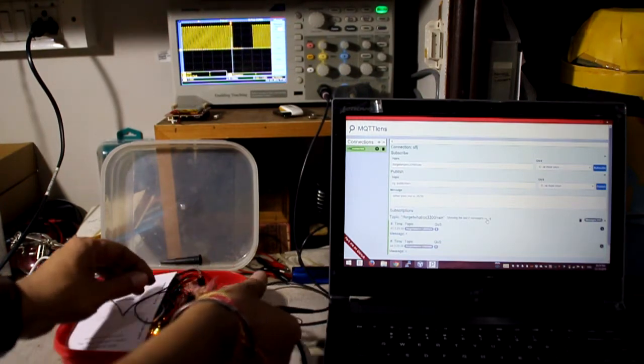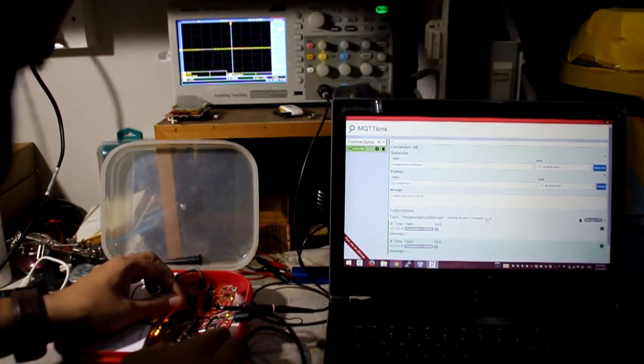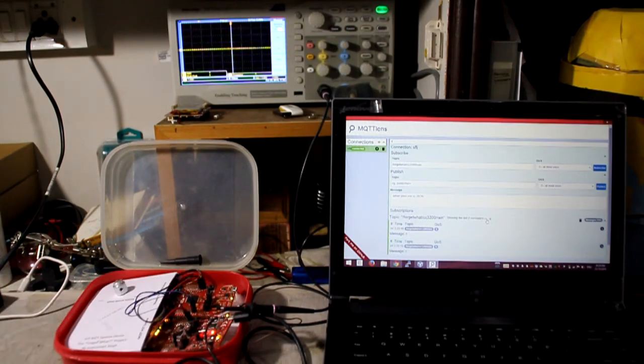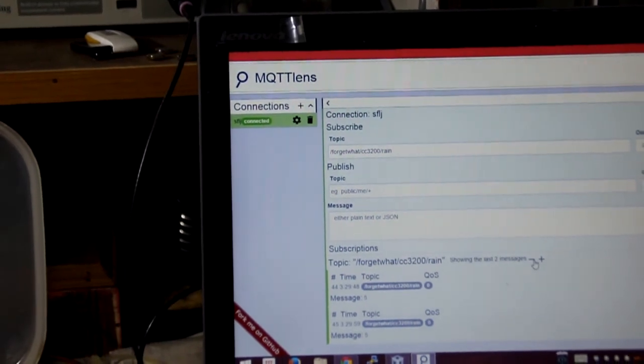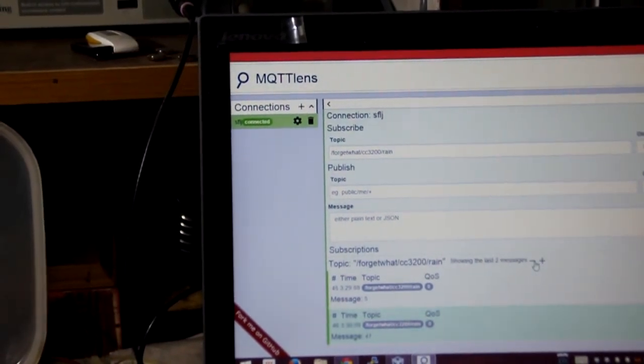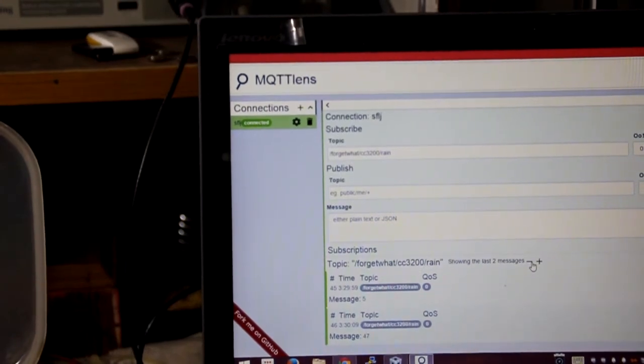Now if I disconnect this and connect it to the CC3200, it's easy to see. Let me zoom in, and now you can really see that it's updating those values. I'm going to really lower it down, so now it's going to give me a smaller value, in about there we go. So it's really low, and if I really turn up the potentiometer, now it's going to generate a higher frequency and it's going to update that frequency onto the system.